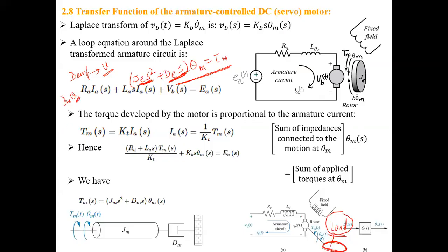So whenever there is velocity, there is always damping. Keep that in mind. If the system is moving, there is always friction, right? You're right, Jane. So whenever there is velocity, there is always D, damping, there. That's why you have two terms here, but no K. Now the question is, what are this theta M and TM?